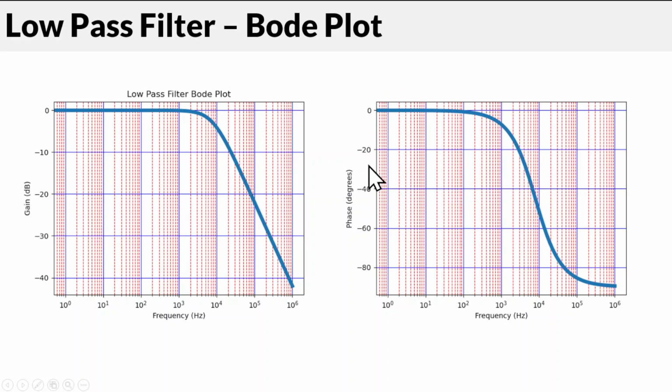Likewise, the output signal remains fairly in phase, close to 0 phase difference, for quite a way, up to hundreds of hertz, even into the low thousands of hertz. There's not very much attenuation. It's only when you get above that 1 over RC frequency that the output voltage drops really suddenly.